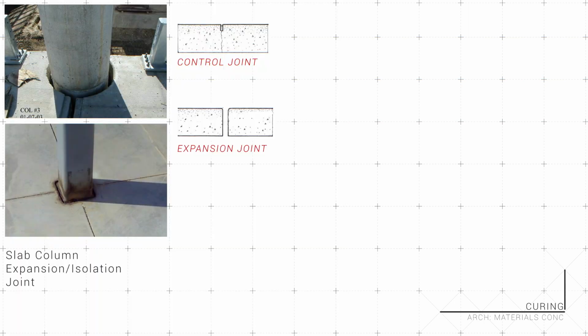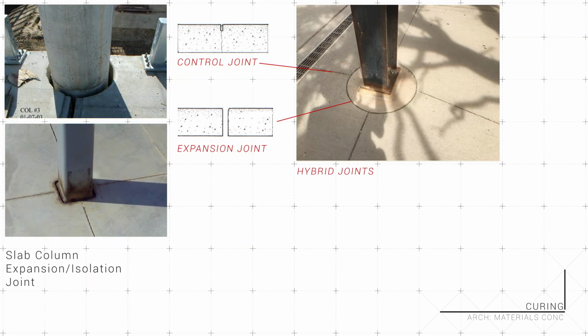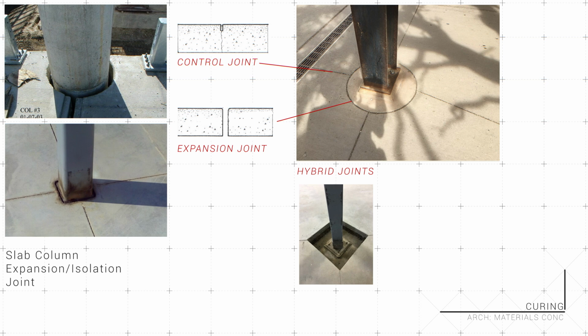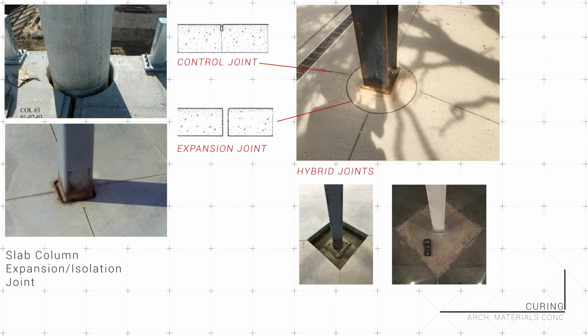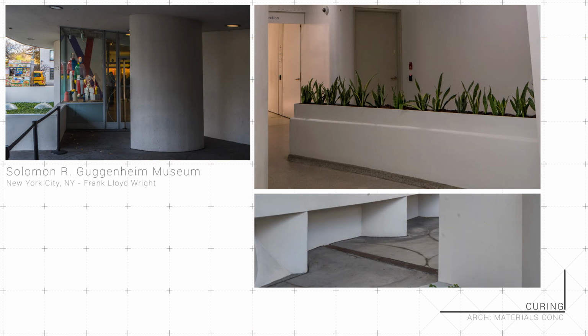Recall the control joints from a bit ago. Combining those with expansion joints around columns is an even more advantageous system. At ground level on grade, columns touch the ground and are isolated completely with a large gap between the column and the slab. This is then filled in with its own smaller slab, leaving an expansion joint. From there, control joints radiate out to concentrate shrinkage cracking. So when you see groupings of detail and seams around ground connections, it's not just for aesthetics, but a symbiotic relation of grouping details and designing around real-world building problems.